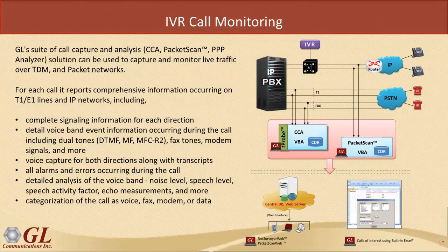For each call that we capture, we can provide a comprehensive report that shows the complete signaling for each call, detailed voice band event information such as dual tone, fax tones, modem signals, and detailed analysis of the voice band, such as noise level, speech activity factor, echo measurement, etc.